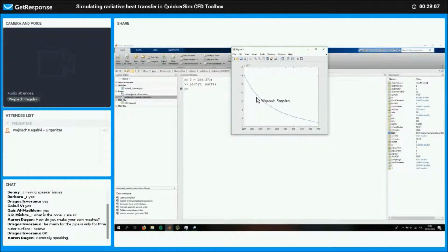As I said, it changes quite substantially over the range. I mean, this isn't even 0 degrees Celsius. These are in Kelvin, by the way, I hope this is obvious. All the temperatures I'm going to be using today are in Kelvin, because the radiative fluxes are computed based on the absolute temperature of a body or a surface. As you can see, over the span of about 90 degrees, the viscosity of water changes more than threefold. So this is a very important effect.